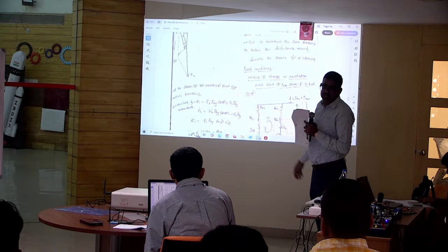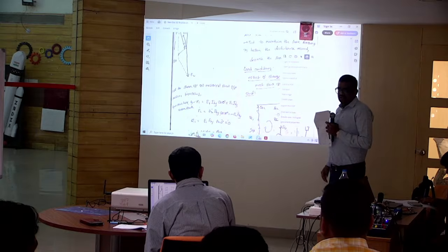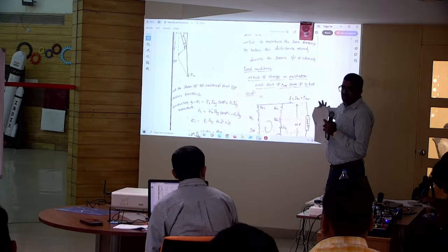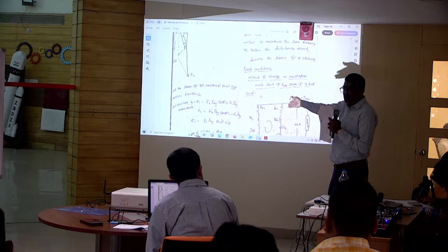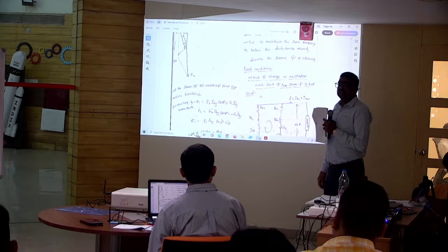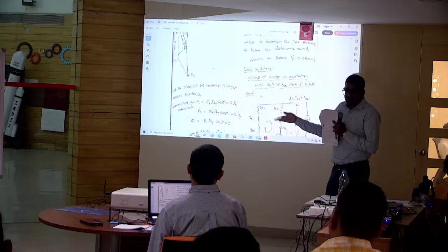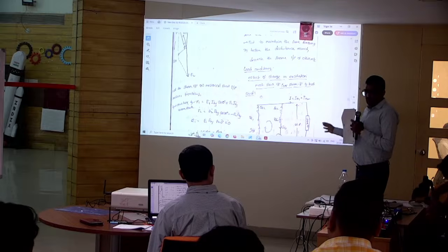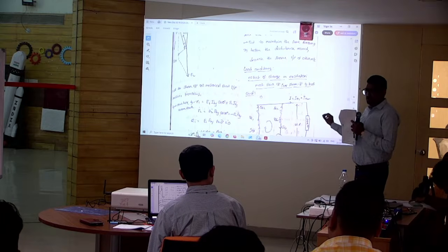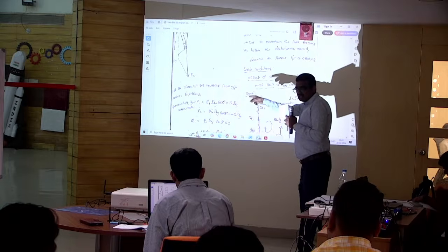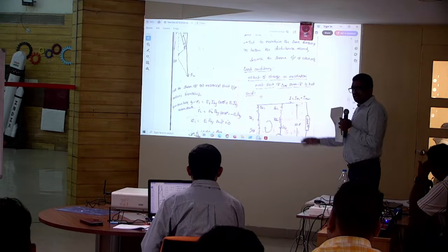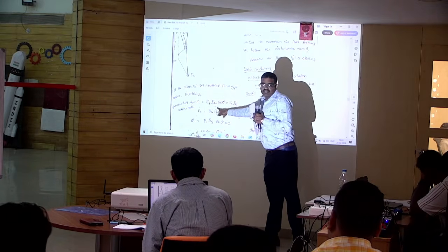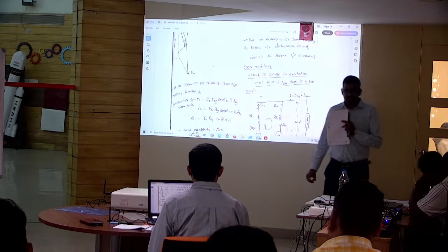Synchronizing current, phase relation. When both machines are operating at no load and the mechanical input of one machine is changed, consider the synchronizing current with respect to the active component. Under no load, it is mostly and ideally zero power factor operation. Now the synchronizing current is in phase with E1 ideally, so the angle between E1 and ISY, the synchronizing current, is ideally 0.